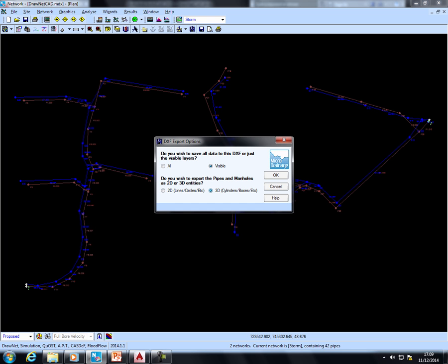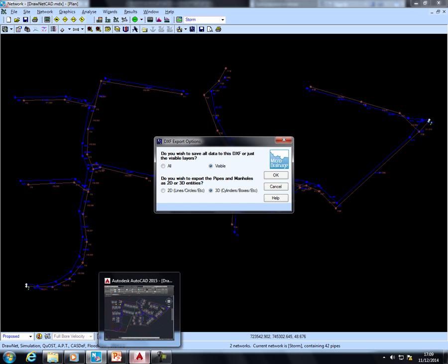And then you can set up meta tags within Civil 3D to add on the thickness of the manholes, the concrete surrounds, etc. You can set up a library to then have the external dimensions as well as the internal hydraulic dimensions associated with the networks. And this is where the real power comes to play.